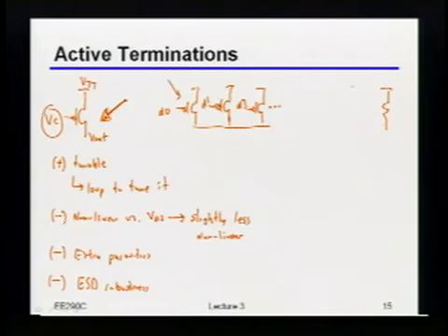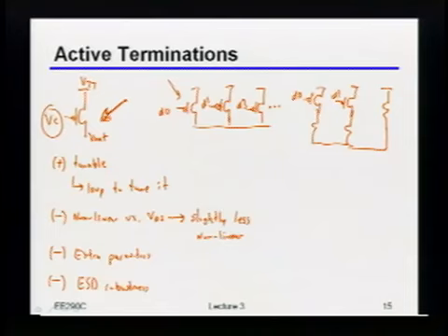So if I really do that, and by the way you typically end up doing something that looks sort of like this. So those other legs that you do the tuning on, you actually also put some series resistance in them. Okay, and then again, these are, of course, some digital codes over here. So that's really the reason why this turns out to be a little bit better. Because what I can basically do is I can put kind of a resistor there that isn't exactly the resistance I wanted.